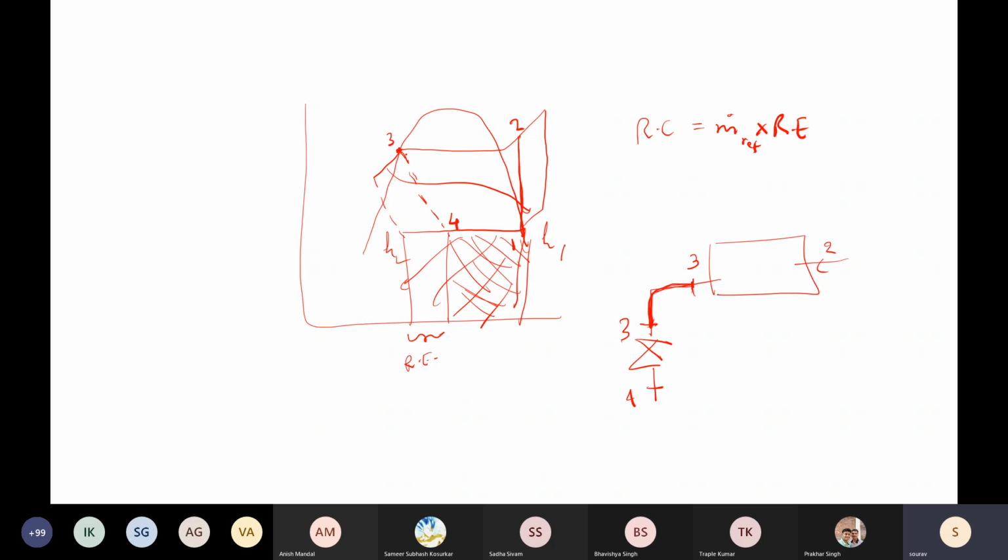Okay, so if you have a small amount of pressure drop within the tube which connects the condenser outlet to the expansion device, you will reach the two-phase region if you were using the standard cycle. So if you had saturated liquid at the exit of the condenser, even the smallest of pressure drop will lead to the liquid line itself having some vapor because you will reach here. Now what you're doing is you are subcooling it to this level.